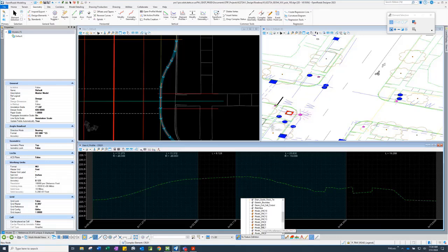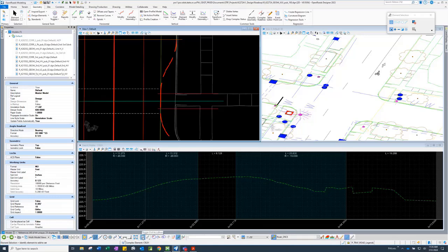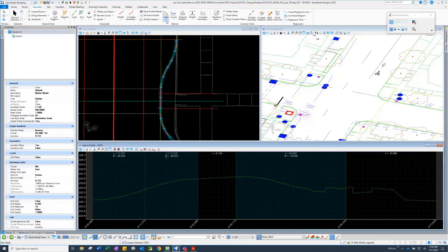So we're going to go back to level 5. In here, I have defined my pedestrian path, but I don't see it in my profile. One of the tricks I use is I will turn on Civil AccuDraw. I will activate the profile view, and I'm just going to draw a profile line. You put the mouse focus in the profile view by clicking on the title bar of View 4. You can click in the window too, it doesn't matter. But yes, I made it active.